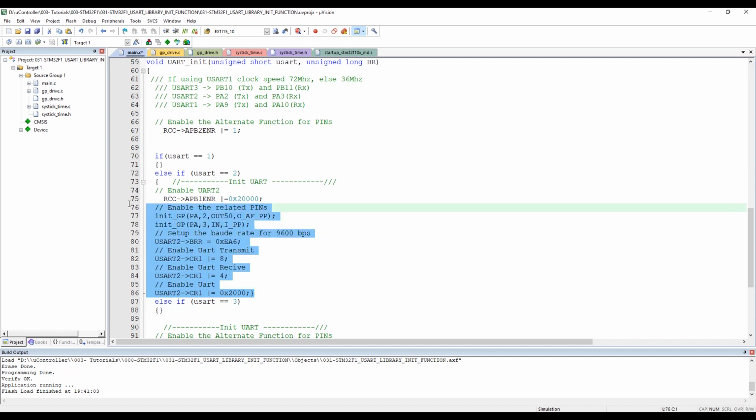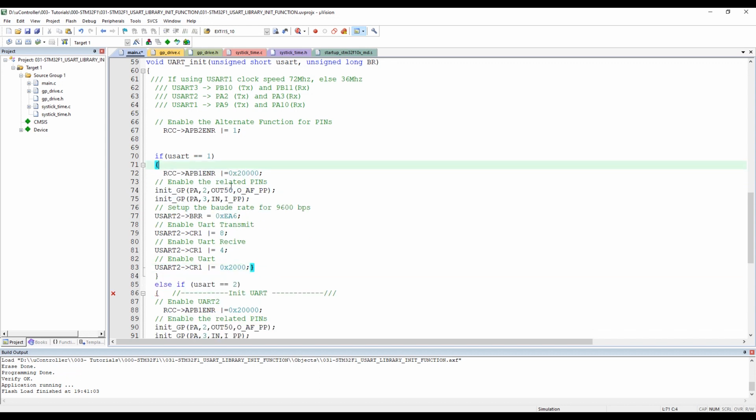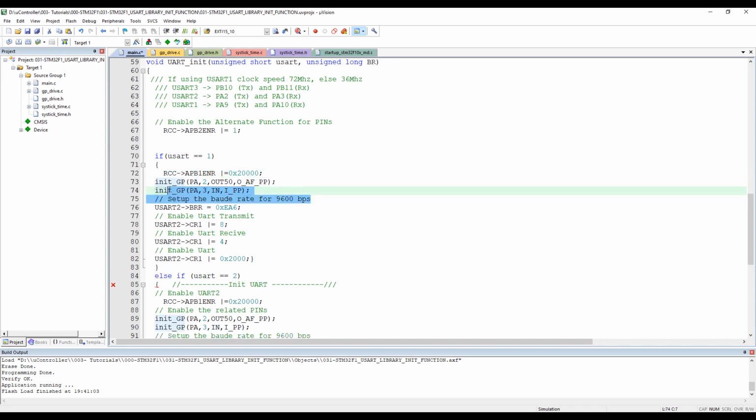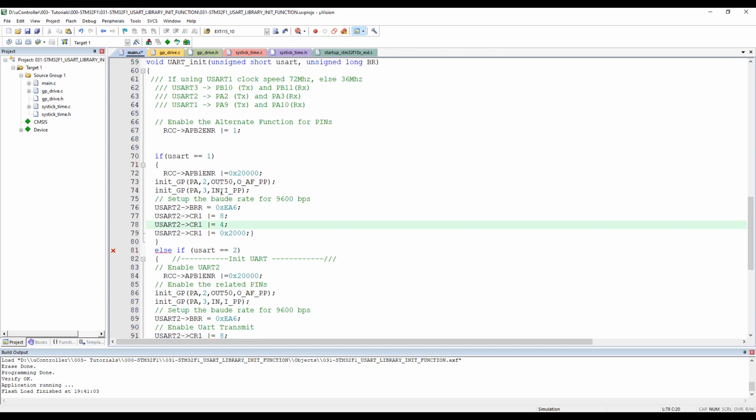So what we have to change here, so this is UART2. I'll be removing all the comments here because we don't need them anymore, so we try it for 1. I will keep this setup just for understanding purposes. Okay, and what I have to do now is, instead of 1, I put 3. So here this is 1 1 1 1, and to enable the UART1 we have to go not to APB1 enable but APB2, as we have seen.